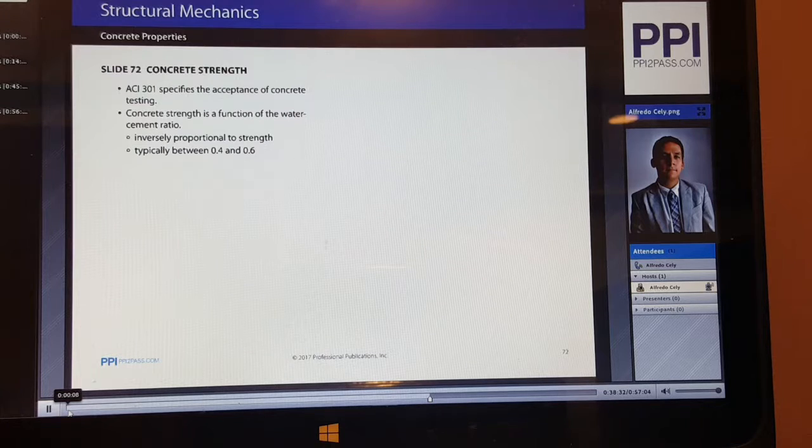For concrete strength acceptance, a single strength test is the arithmetic average of concrete compressive strength of at least 2 6 inch by 12 inch cylinders, or at least 3 4 by 8 inch cylinders. Single strength tests are generally performed at 28 days. The concrete strength, or the specified concrete strength, is known as the f'c.